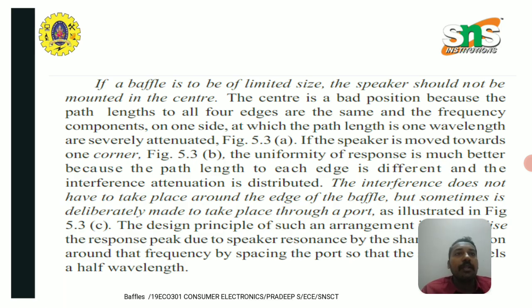If a baffle is to be of limited size, the speaker should not be mounted in the center. The center is a bad position because the path lengths to all four edges are the same and the frequency components at which the path length is one wavelength are severely attenuated. If the speaker is moved towards one corner, the uniformity of response is much better because the path length to each edge is different and the interference attenuation is distributed. The interference does not have to take place around the edge of the baffle but sometimes is deliberately made to take place through a port.